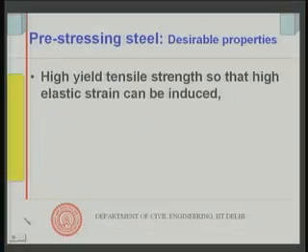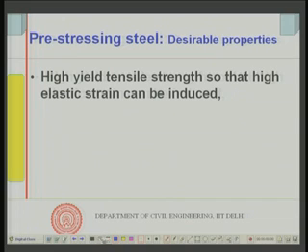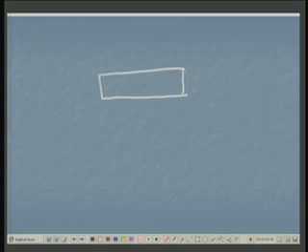using some steel. So, what you do? You pull the steel wires or strands, and then anchor them into the concrete. Pre-stressing would look something like this. We might have seen it before, but let us recall. Let us say this is your concrete specimen, a beam element, and I pass a wire through this. A simple case: I pass the wire through and pull it. After pulling, I anchor it up here.